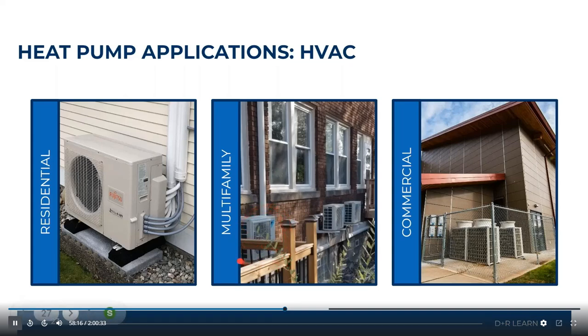These heat pumps, I want you to remember what they're doing is they're drawing heat from the outside air in order to perform the function that it's designed to do. So if you install this system where it is unable to draw in an adequate amount of air, then you're hindering the performance of the system.